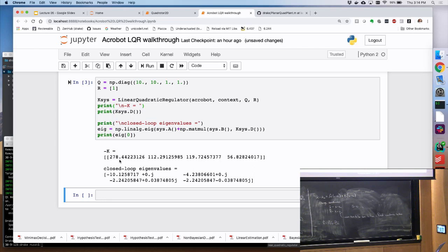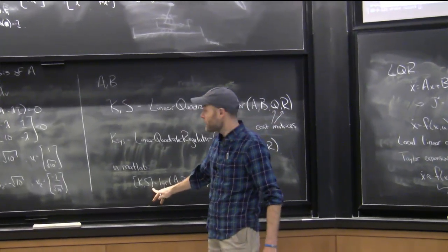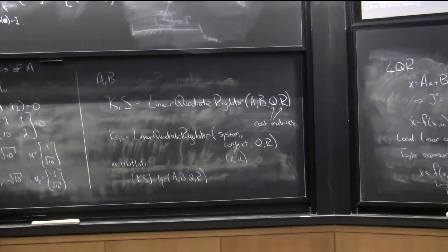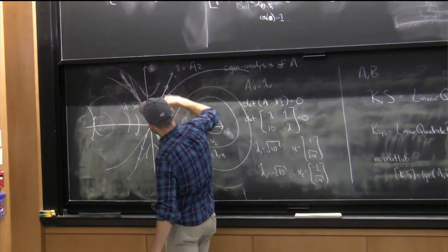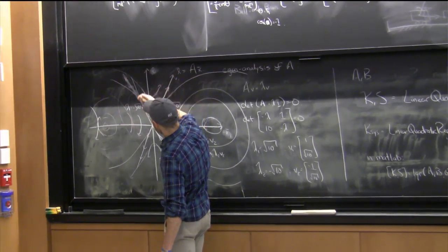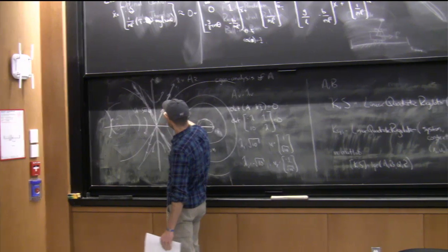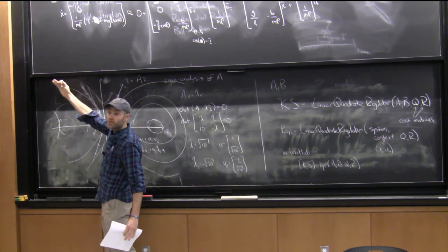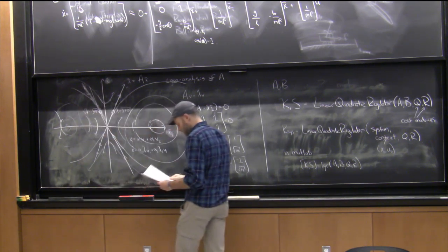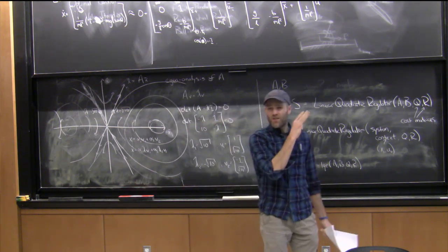The output, of course, is two things. I didn't actually plot it there, but it's K, and it's also this S, which is my cost to go. The contours of S are a cost to go that goes like this, and it similarly is going to capture the fact that it's cheaper to be here, where you can ride the dynamics into the origin, than to be here. So it's going to go up more quickly in this direction and more shallow in this direction. So it really does capture the long-term dynamics. So that's really awesome, actually.